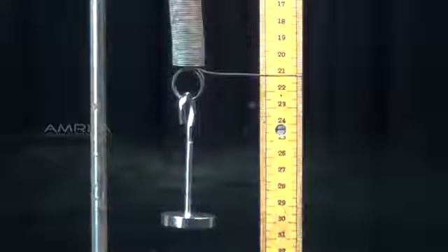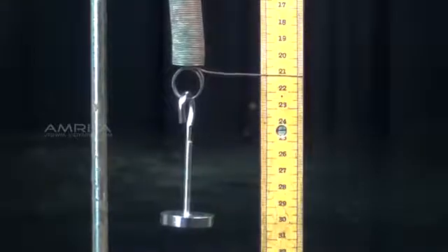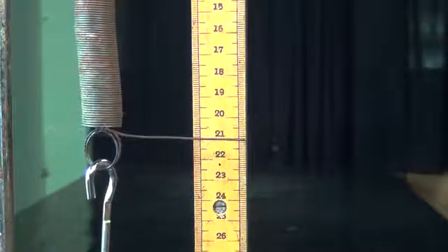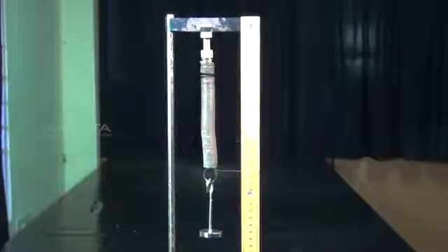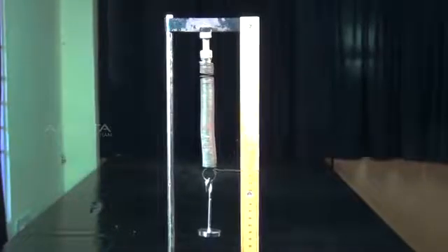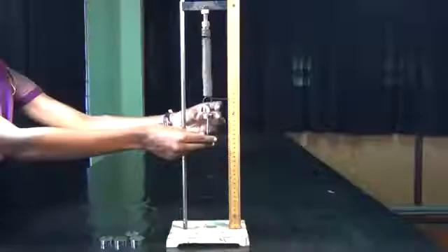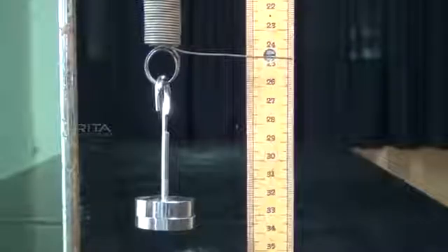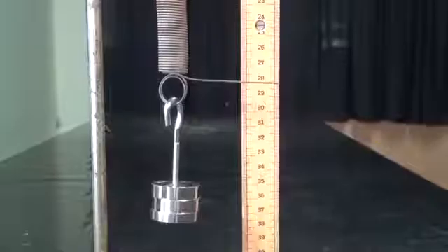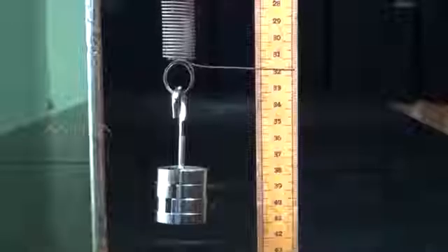Set the vertical wooden scale such that the tip of the pointer comes to the divisions on the scale but does not touch the scale. With the weight hanger alone attached to the spring, the reading of the pointer on the scale is noted. Slotted weights are added one by one to the weight hanger, each time noting the scale readings.